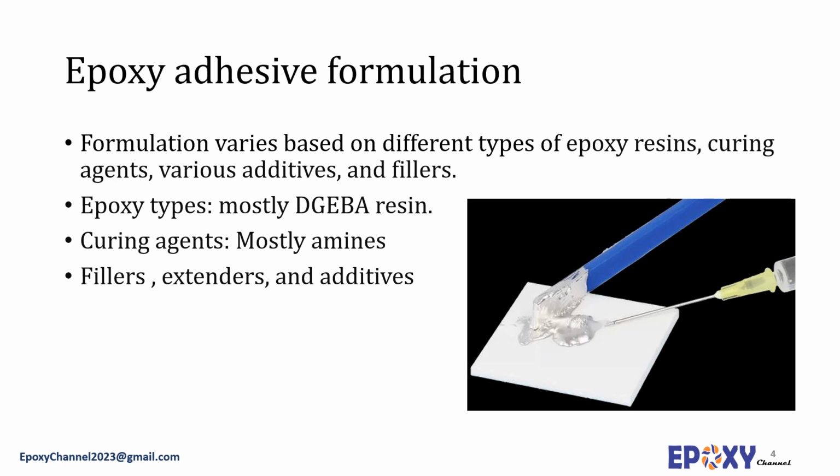In addition to the base epoxy binder and the curing agents, the incorporation of different fillers, extenders, and additives can result in some considerable improvement in the epoxy adhesive's behavior. The most important roles of the additives for epoxy adhesives include viscosity and flow properties amendments, shrinkage reduction, toughness enhancement, amending thermal expansion coefficients, modifying exothermic characteristics, and of course, cost reductions. Occasionally, pigmentation in the epoxy adhesive system is conducted separately in the binder and the curing agent, often in different colors. This allows the visual identification of a proper and homogeneous mixing.